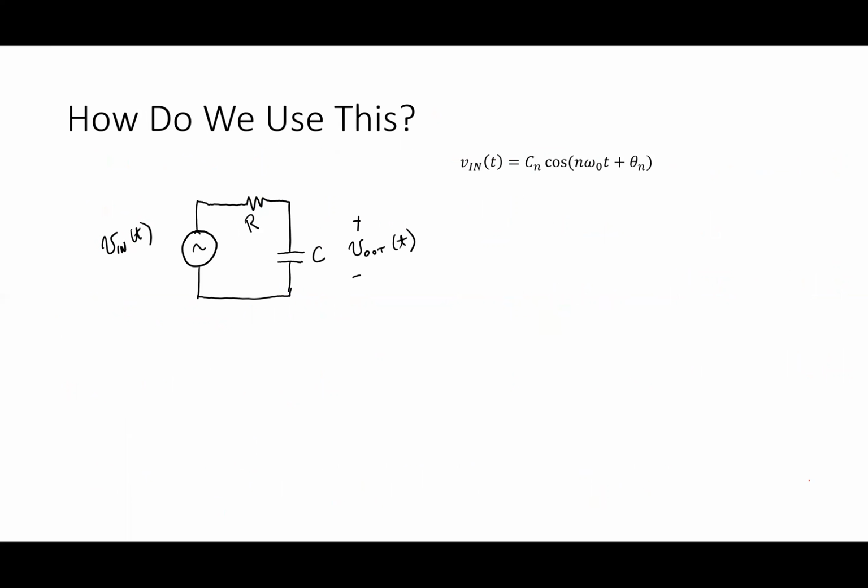So when I have a circuit, what that says is something that you wouldn't normally do, but I could take the differential equation and use everything we just did to transform the differential equation into the frequency domain. All right, so what's important about that? In this case, if I got the differential equation and I do KVL to get that, you should be able to do that, I would have Vin of t is equal to RC dVout by dt plus Vout, right?